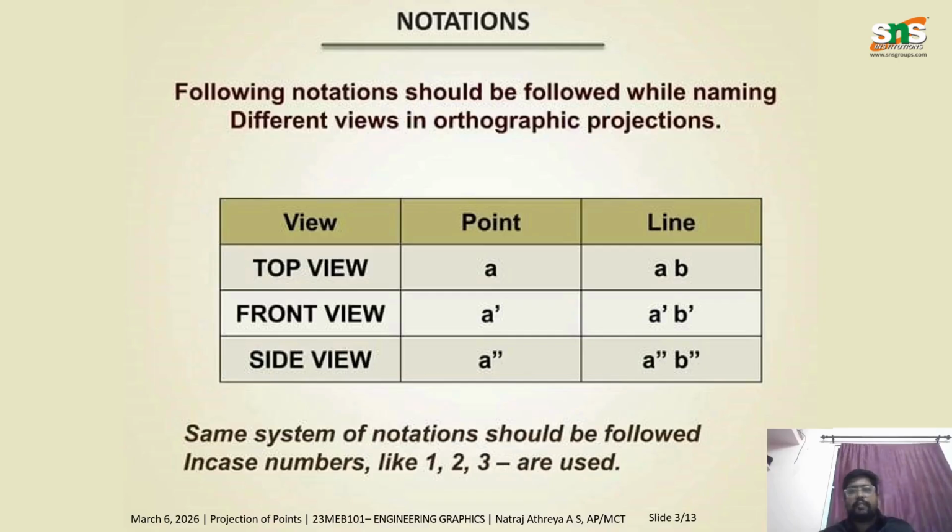Imagine you have, let's say, a box or whatever object that is. What are the different ways you can look at it at 90-degree angles? That is called orthographic projection. You can see it in a 3D way, rotating it around, or you can see the 90-degree views of the same object. First, you can look at the object from the top. That is the top view. Then we have the front view. The opposite of the top view is the bottom view, so you can look at the bottom, and then you have the front view.